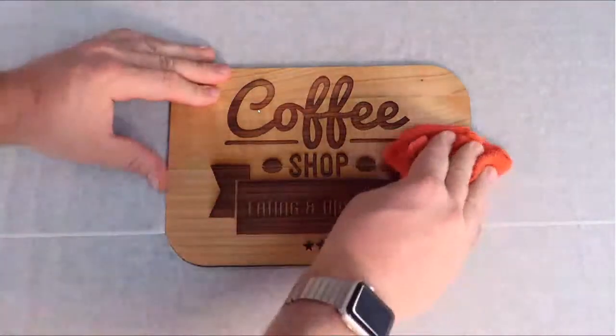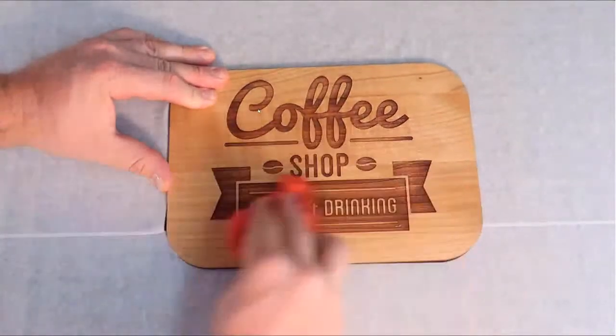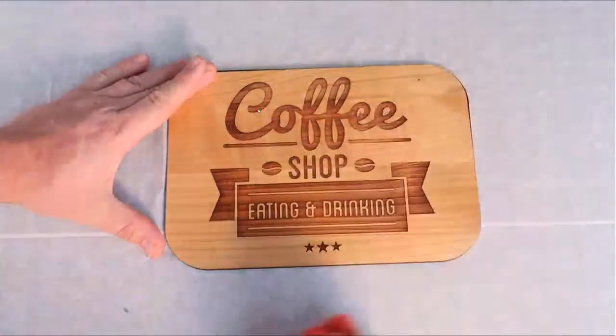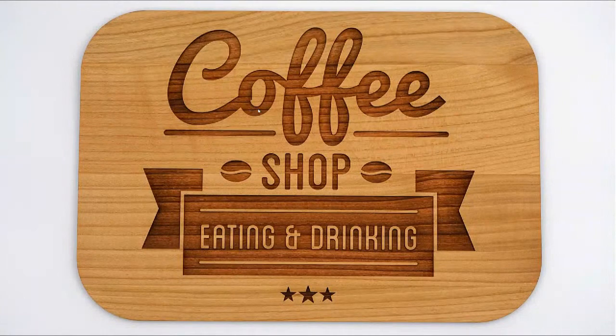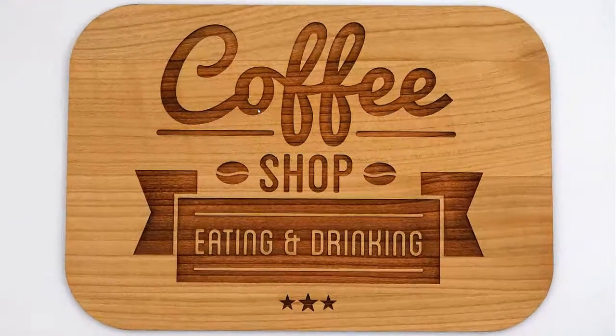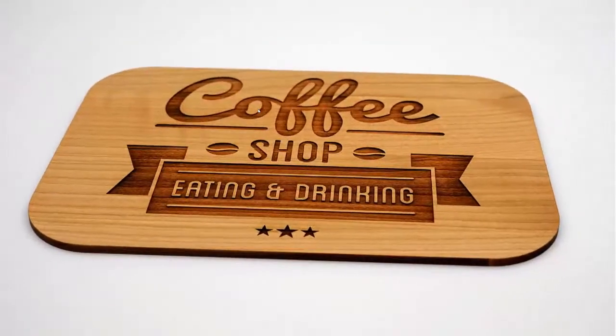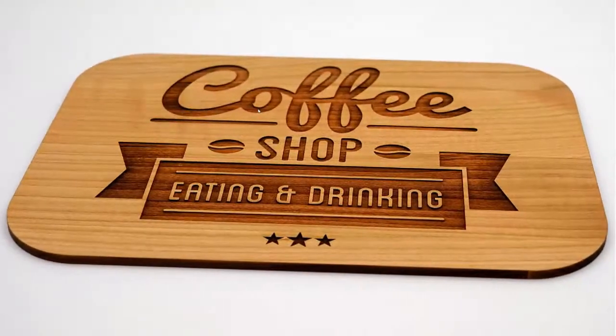Now with the finished wood that I have here, you can see I'm just taking a damp cloth and I can wipe off the surface for the finished result within seconds. If I have to sand this afterwards and then re-lacquer it, it's a lot more time consuming. And if there's a lot of detail in the signage itself, you can actually break little pieces off with a sander, so it's hard to do that. So I do suggest that the wood is finished. I do suggest that it's a lighter colored wood if you just want to use natural wood to produce the contrast.